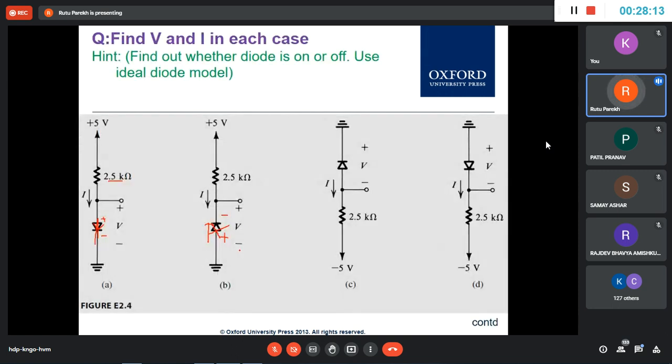So across the diode, see, this is 5 here. But across the diode it is like this: this is negative, this is positive. So you don't say -5. We say 5 because the diode is here this way. We will not go and reverse the diode. So this is plus, this is -5. So across the loop it is 0. This is +5, this is -5, which is 0.